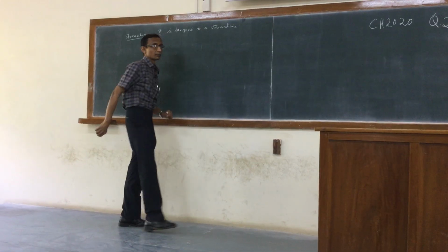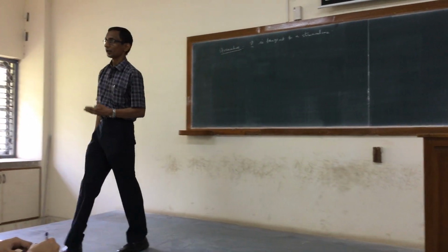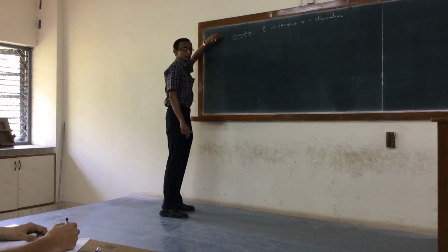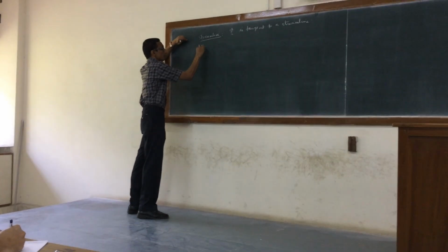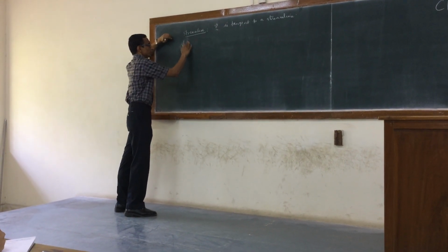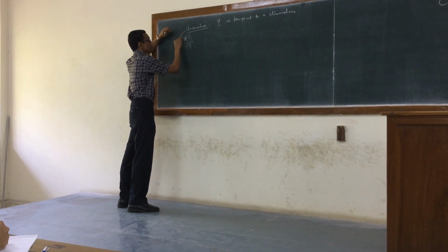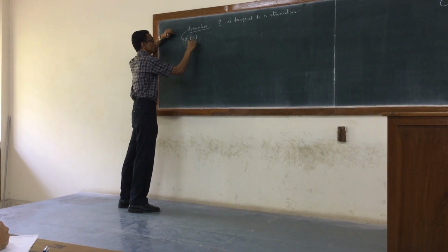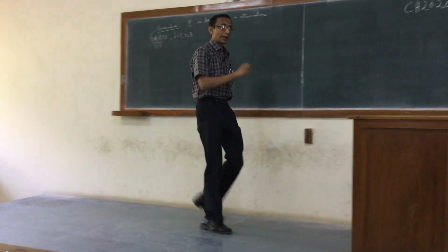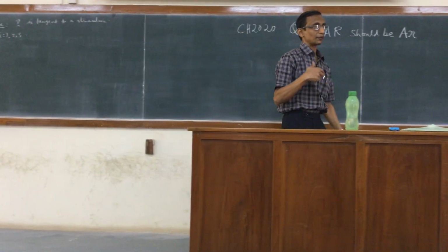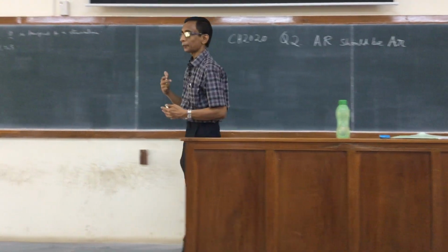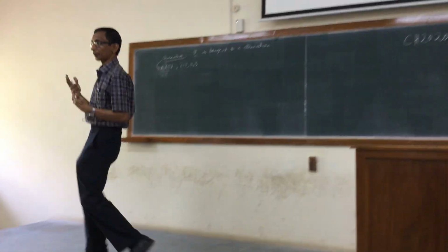A curve in space, so that the tangent vector at any point on the curve will give the velocity vector at that point. So I can write the defining equations for the streamline. Suppose the streamline is given by x_i of tau, where tau is the parameter that will describe the streamline. We've seen that any curve in space, a very general way of representing it, is by a parametric representation of this form in three-dimensional space.